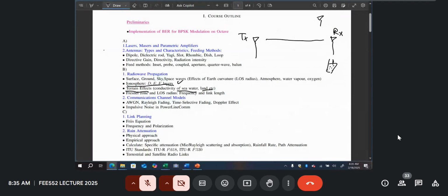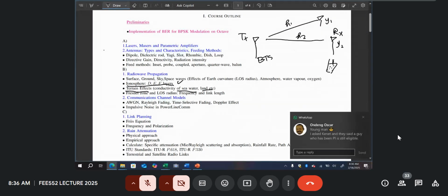So when you're receiving your signal from the BTS to your phone, there's path 1 and path 2, because you have 2 antennas inside your phone, so they receive the signal differently. So we can say this path here, the channel, can be described as H1 and here H2. What you're receiving here is Y1 and here is Y2, because there are different physical antennas in the phone.